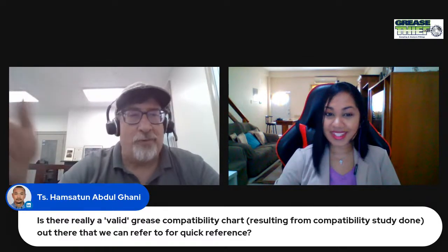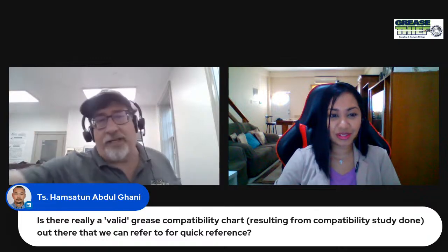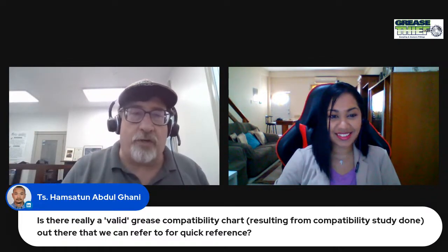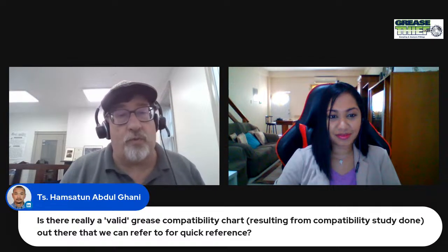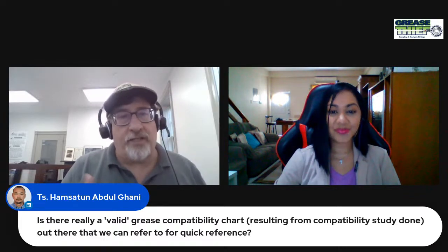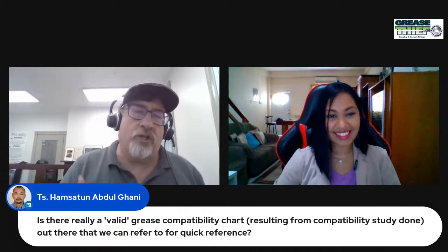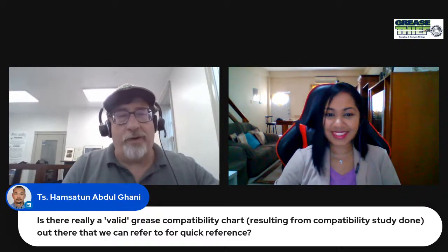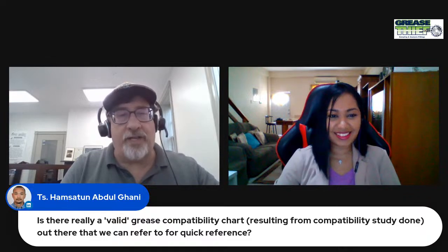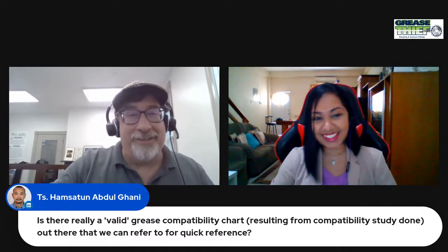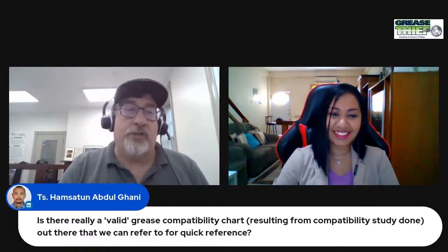We know that, right? We know we can't take a PAG and mix it in with a SHC PAO. So we have to have the same concern about the grease base oils as well. So base oil compatibility, chemistry, but also viscosity. I've seen sometimes people send some greases to me and they're like, "You do a compatibility study," and then I look at the product data chart and I'm like, "Well, the one grease you're giving us is 1,500 centistokes at 40 degrees C, and the other one is 68. So no, they're not compatible. One of them must be wrong."